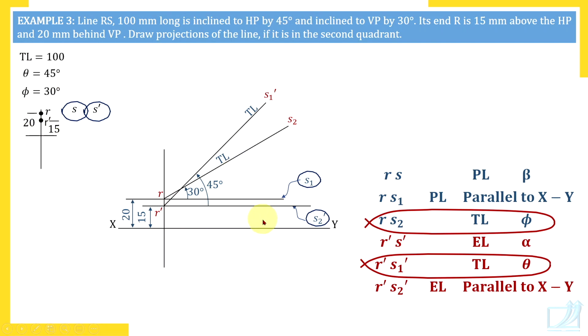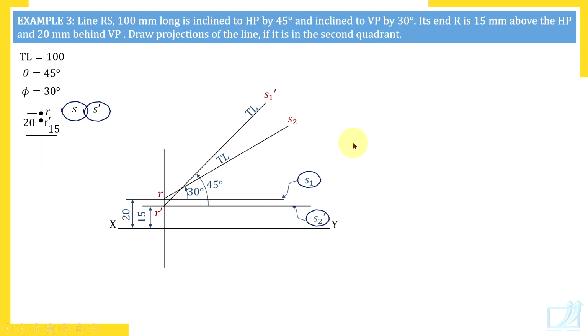Now measurements are over. Remaining construction is purely construction work without any measurements. Horizontal, vertical lines and rotation of EL or PL. Let's do that. So through S2 horizontal line, which is the other point on this line? S. S and S2. Remember B and B2 on a horizontal line. Here only the letter is changed. Similarly, S1 dash and S dash on a horizontal line.